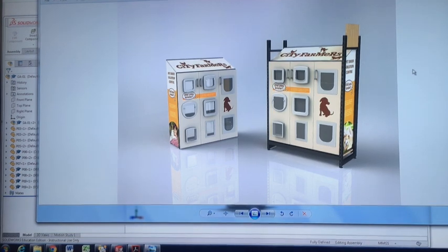So in your renderings, there's a few different things to consider. First, there's your materials and your appearances. That's what you add to the actual models. Then you've got things like artwork and decals. So this City Farmers stuff and the stuff on the front and the sides, that's created in Illustrator, exported as a JPEG, and then used as a decal onto those surfaces. I'll show you how to do that. Then you've got the scene. The scene is pretty much the background, the floor, the walls, and that scene can also include the environment and lighting.